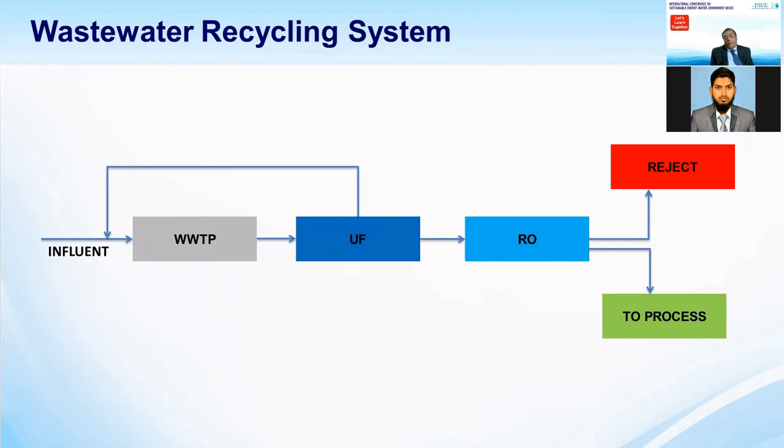Because like a doctor, the technologists of water treatment also observe from the data what contamination can damage the RO membranes, and what contamination can damage the UF membrane. Now, if you see here, we first have to achieve process control of the wastewater so that we can make water fit to feed to UF. And from the UF outlet quality, we have to ensure that water is fit to feed the RO membranes. Those are all integrated system parts, and we have to meet the feed water conditions for all.